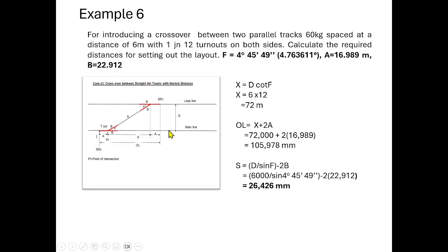Many times even the open line engineers sometimes have problems in this kind of crossover. There will always be some kink. When the train is negotiating the turnout, there will be more jolting, and they can check it. So they can work out this overall distance, whether the relative position is okay or not. We have to check, or otherwise slightly shift it to get the required distance. But whatever we do, it is better to do it in the construction itself, in the initial laying itself.